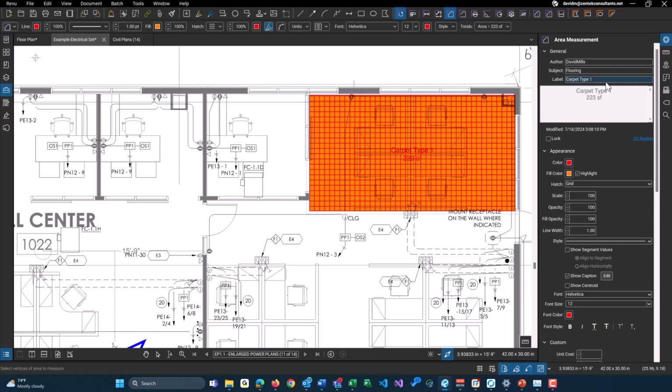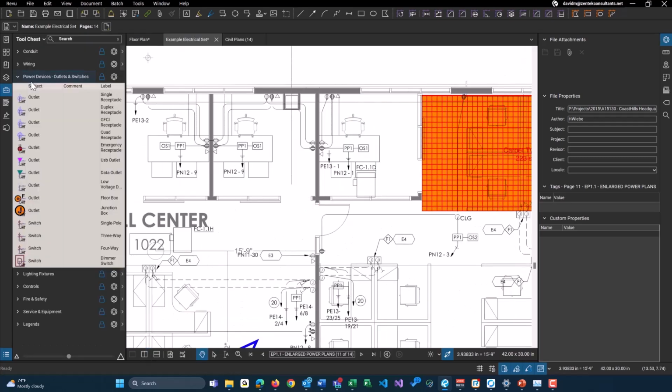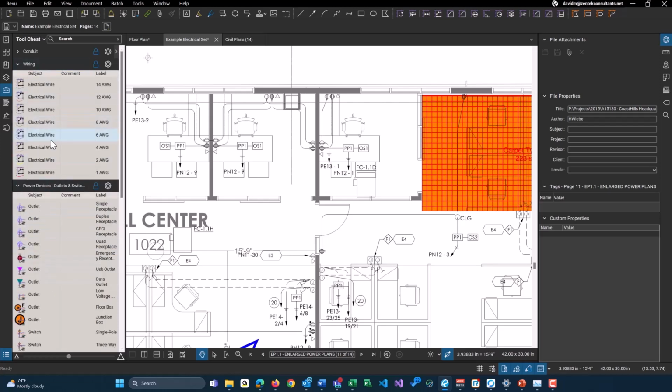Fortunately for you, Bluebeam has built-in tool chest for you. That once you get one of these takeoffs designed to your liking, again, the color, then the naming convention, and more, you can actually add it to a tool chest. And here I'm demonstrating our electrical tool chest here. We got a whole bunch of count tools, which we'll get into momentarily. We have, again, here are some electrical wires. This is actually using the poly length tool that we discussed just a couple of minutes ago.